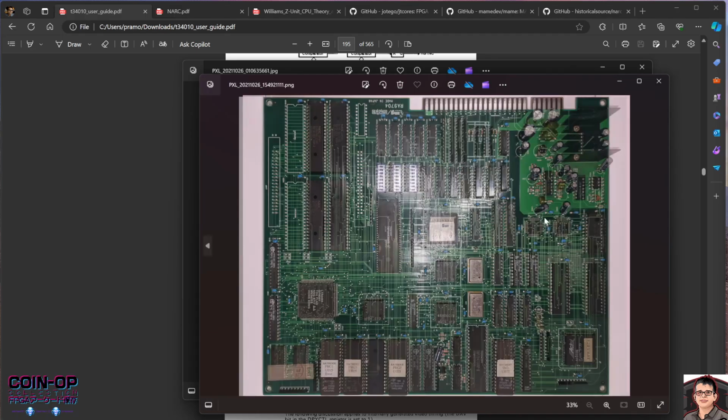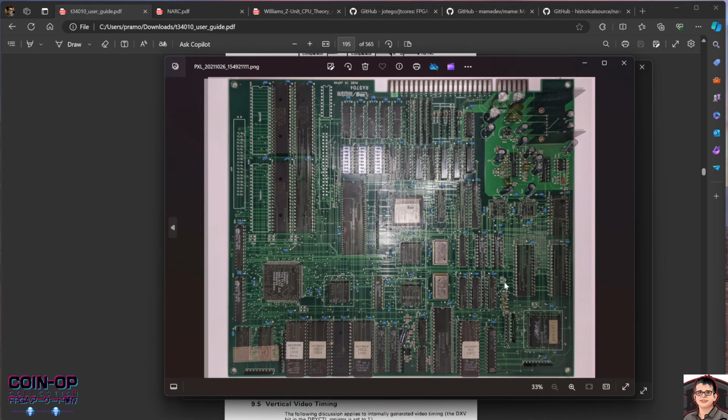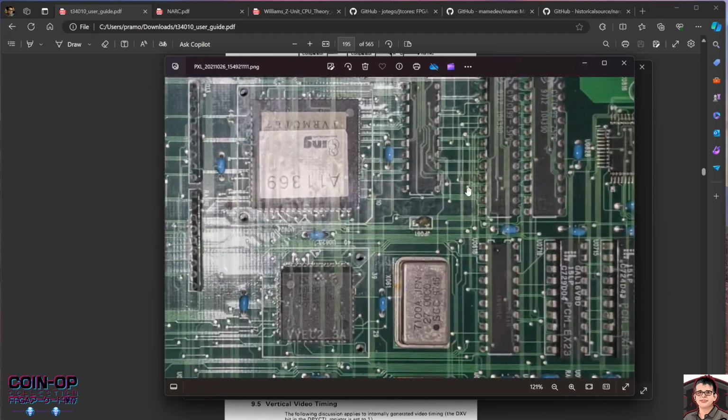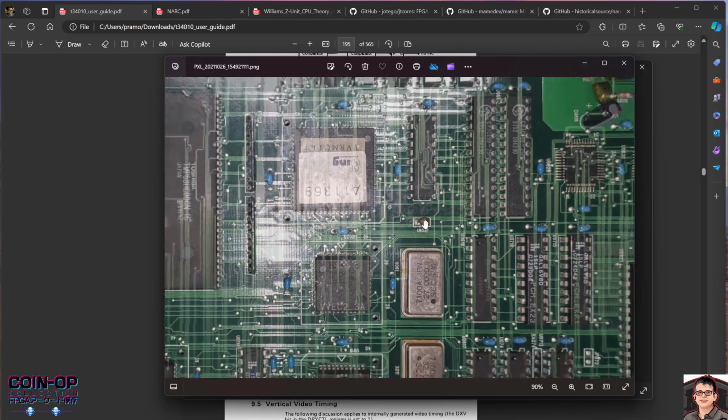Now, what I tend to do after that is I create a merged picture. So I'm going to show you the merged picture. This merged picture has the front and the back aligned properly, and so you can see the through holes, right? So you can see the back traces on the board, because often when we do routing on the PCB, traces will start in the front and then end up in the back and then go somewhere else, right? So I usually do this merged picture.